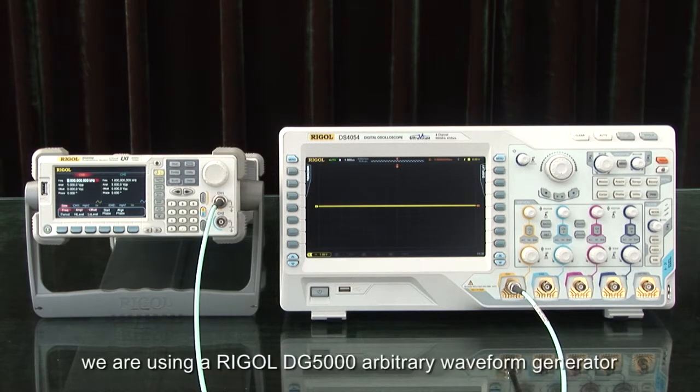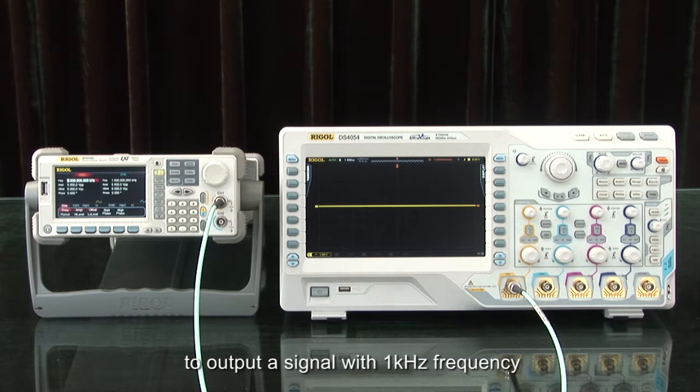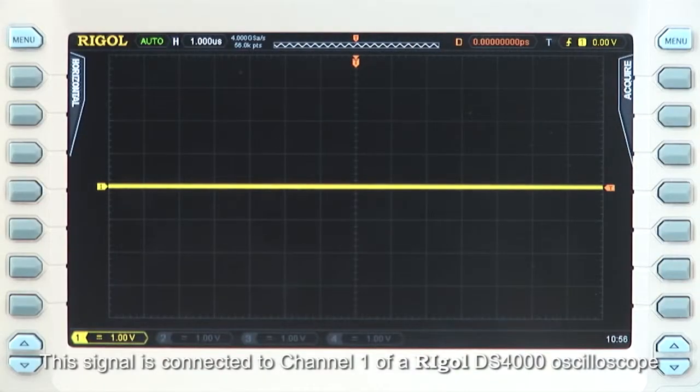In this example, we are using a Rigol DG5000 arbitrary waveform generator to output a signal with 1 kHz frequency, 5-volt peak-to-peak amplitude, and a 10 nanosecond pulse width. The signal is connected to channel 1 of a Rigol DS4000 oscilloscope.